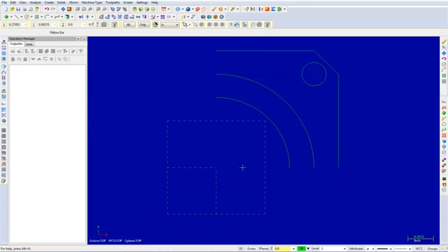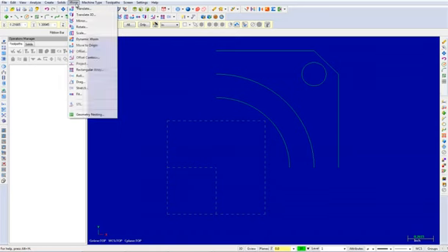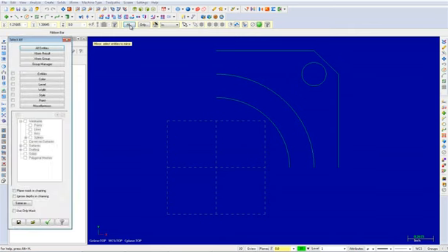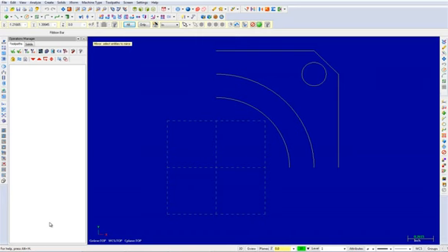In the next step, we will mirror the geometry. The Mirror command allows you to complete the geometry. You will mirror the geometry about both x and y axis. Select X-Form, Mirror. From the General Selection toolbar, choose the All button. From here, make sure that All Entities is enabled to select all entities as shown. You can now select the OK button. Press Enter to finish the selection.